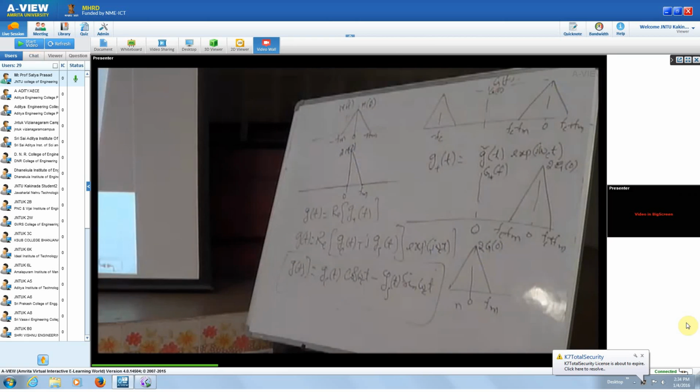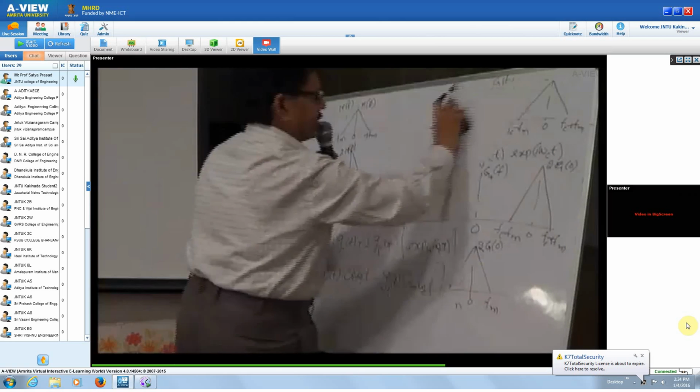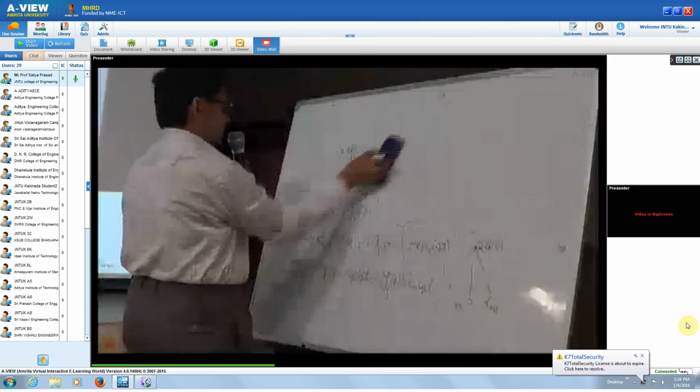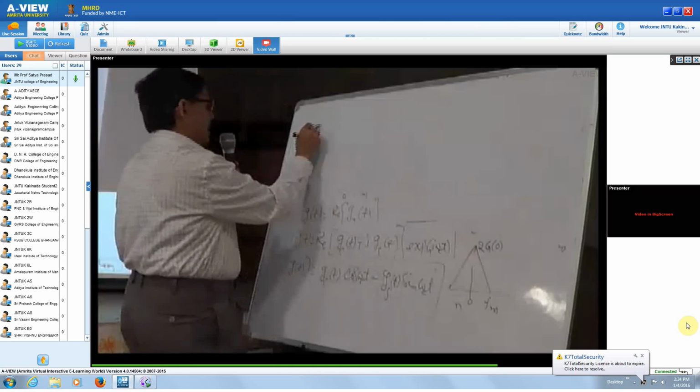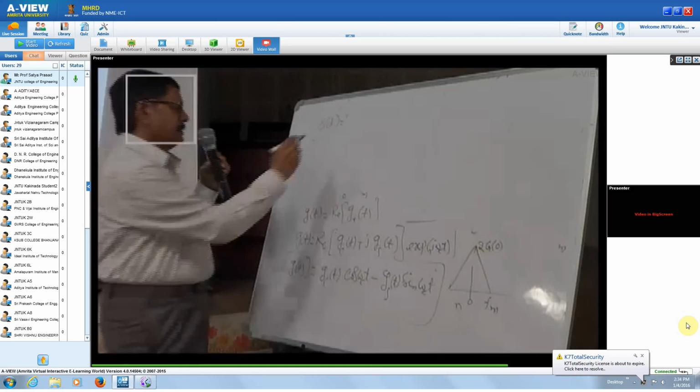Fc to Fc plus Fm, whereas LSB is Fc minus Fm to Fc. So these are the band pass signals. Therefore, our SSB signal, which we are representing as a band pass signal, a generated modulated signal S of t can be represented as